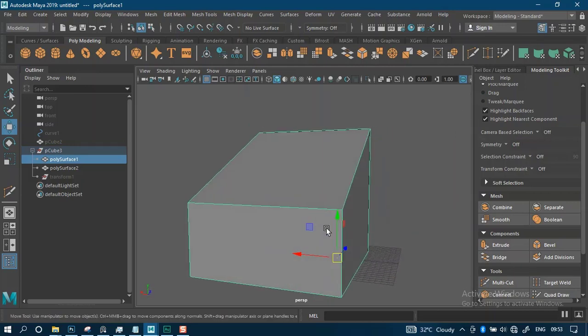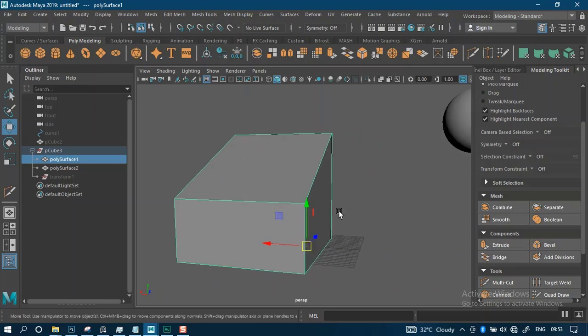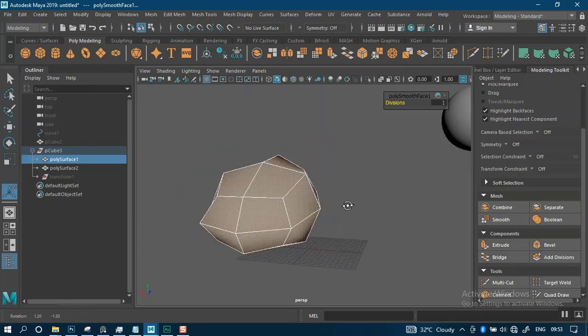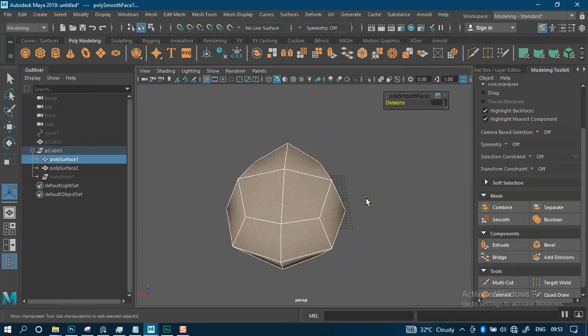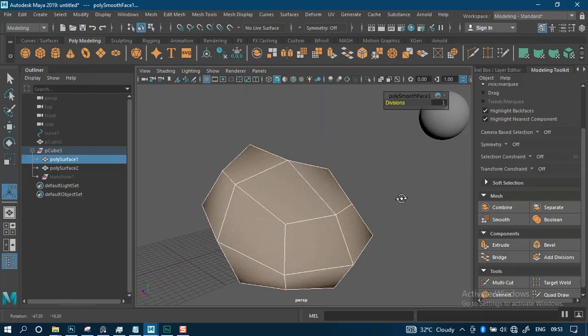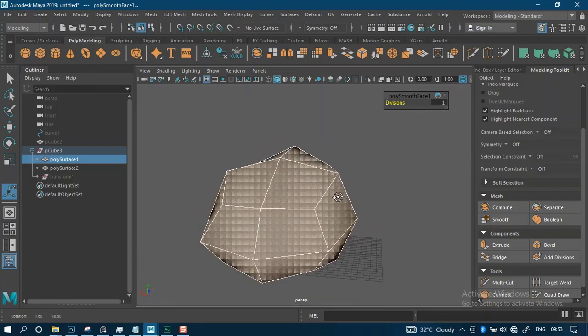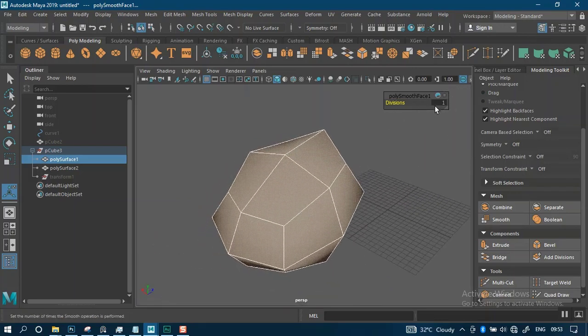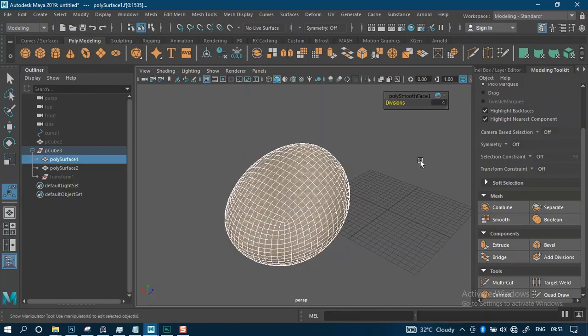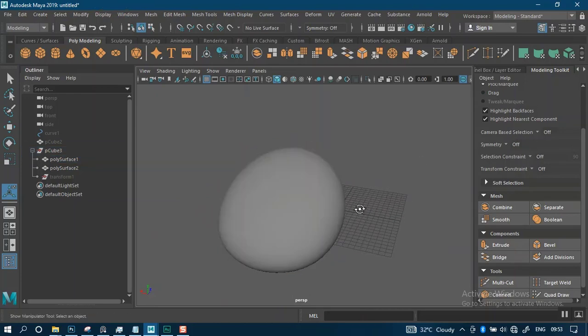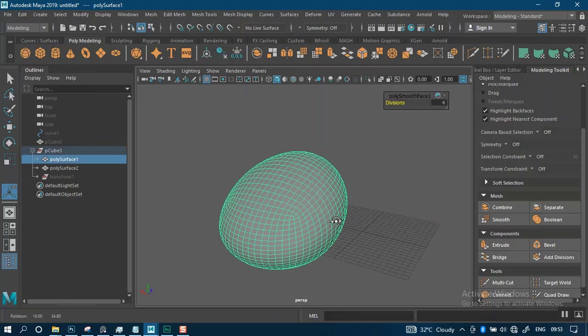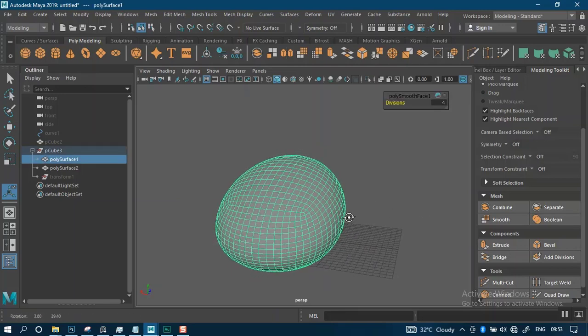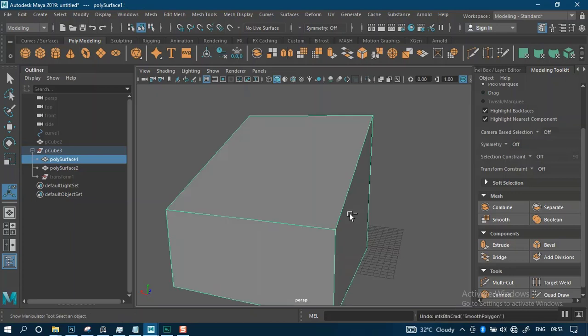modeling in here. And then let's click on this smooth. This smooth adds more subdivision levels to your model. So it's more or less like hitting the 3 key, but this particular one is actually adding the subdivision level on top of the model itself. So we can also increase this value. Let's say put this at 4. You can see how this smooths this out automatically by adding more subdivision levels to it. Let's undo that.